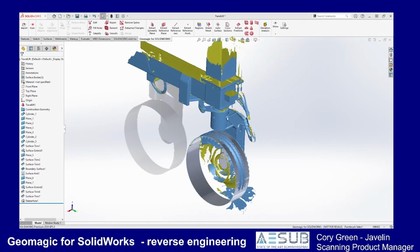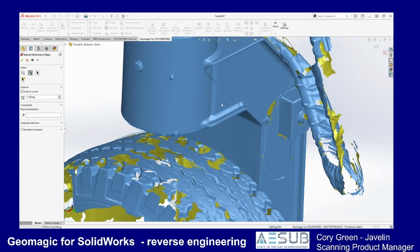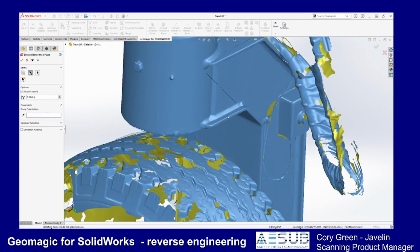Now that we've constructed a block model of the rotating part of the travel lift leg, we can continue with the rest of our design. We'll be building some guarding around this tire. To start that, we'll build a bracket just above this flange. We'll create a reference plane on that flange. We'll make sure that that plane is snapped to the rest of the world.